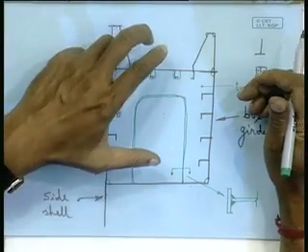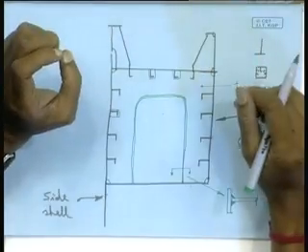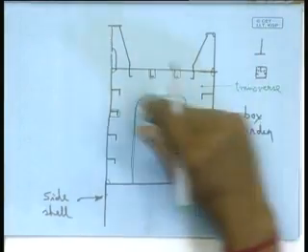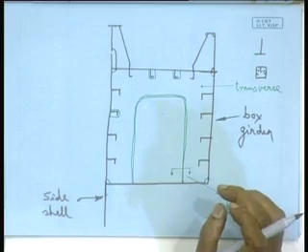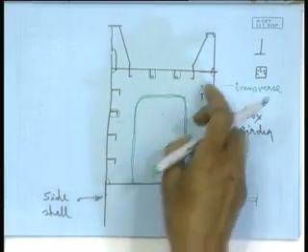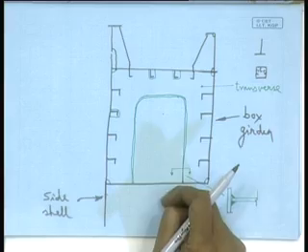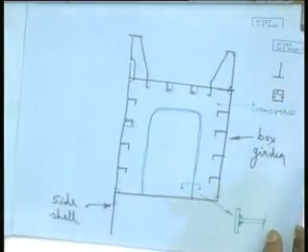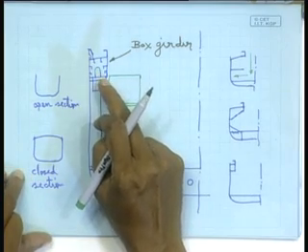You need here the torsion becomes more important, there the bending becomes more important, and so on and so forth. So, this is the box girder construction. This provides you a quite heavily stiffened structure right at the top, at one end of the entire hull structure.